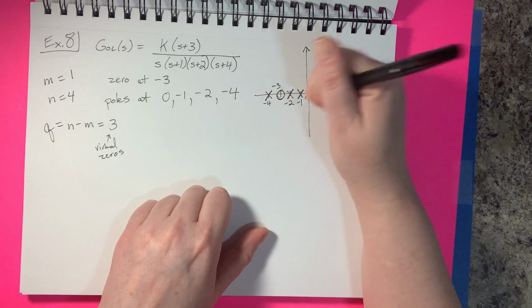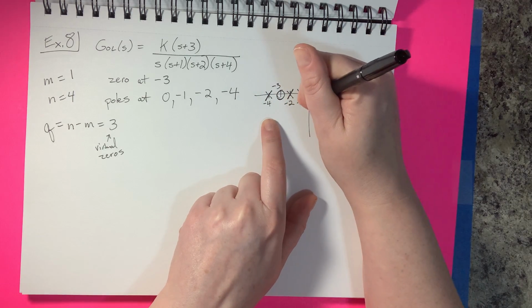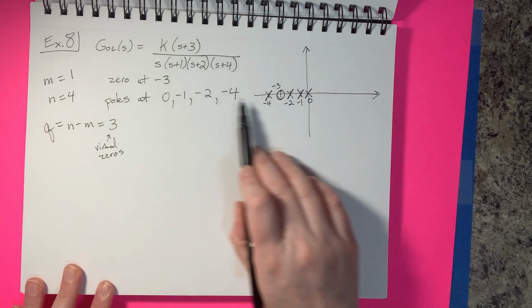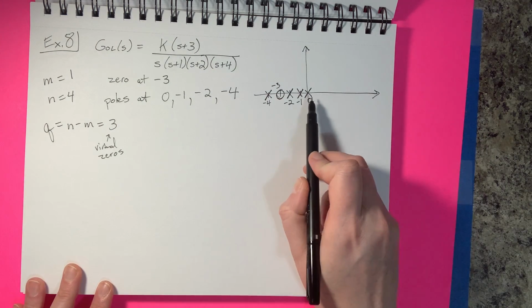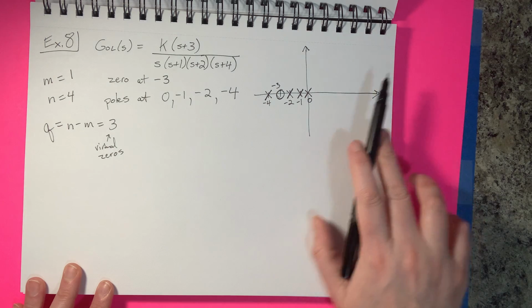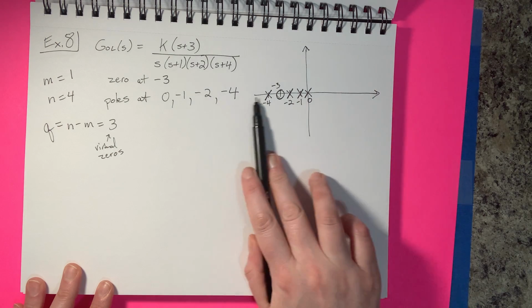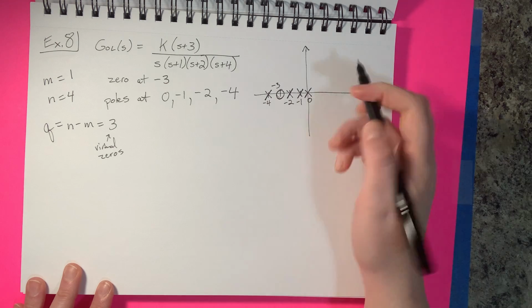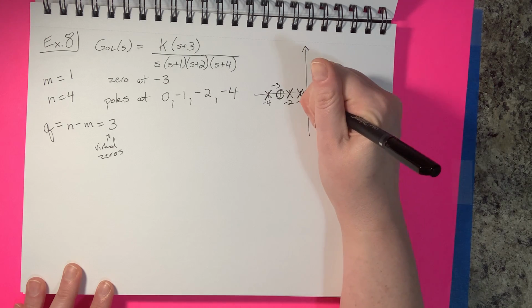So everything out here up through negative 4 is encompassed with a value of a root from one of our sides of our equation. So let's use the real axis rule first because we have a lot going on the real axis. So we move our pen across here, and it's odd once it crosses this first pole.